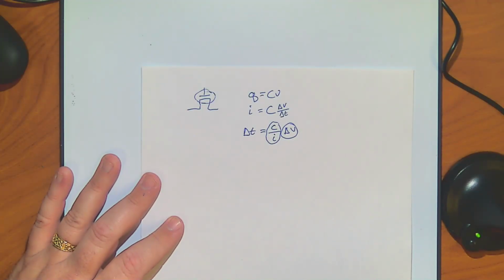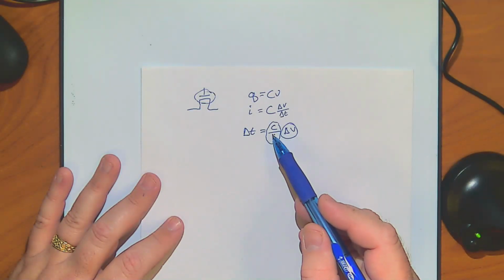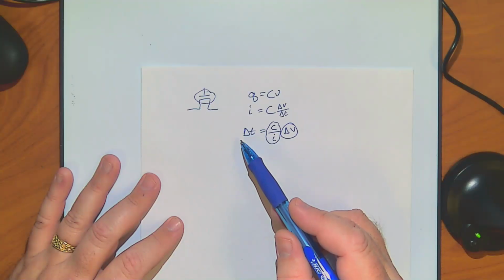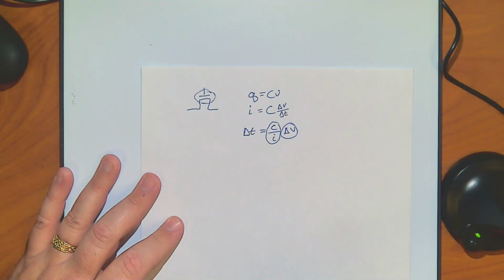small, right? So what happens as the capacitance gets big? The time gets big. So I want a very small capacitance. What do I want with I? I would like I to be big, right? And if you think about it, you're trying to get charges there. So the more charge I give you in a period of time, the faster you're going to turn that gate on. Now that's going to cost you some heat, but it tells you a basic reality.